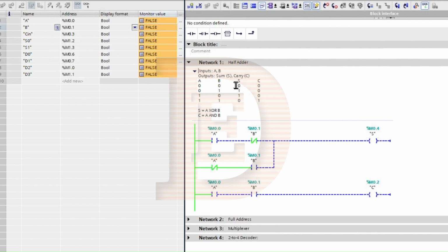With the half adder, we see that the S, or the sum output, is 1 when only one of the inputs is on. If we remember from the last session, that is the case for the XOR, and we know how to build the XOR. In this case, if I have one and only one of the inputs on, S will be on.